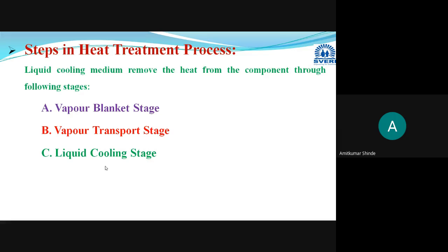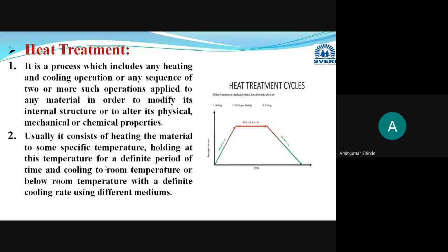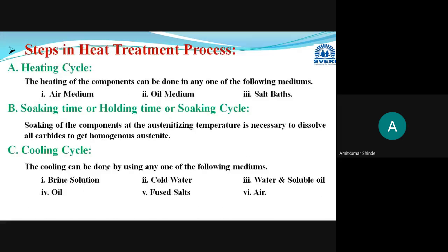In this way the heat treatment process will occur, and these are the steps you have to follow in the heat treatment process: the heating cycle, then soaking time or holding time, and the cooling cycle. We have briefly discussed the different mediums used for heating and cooling.